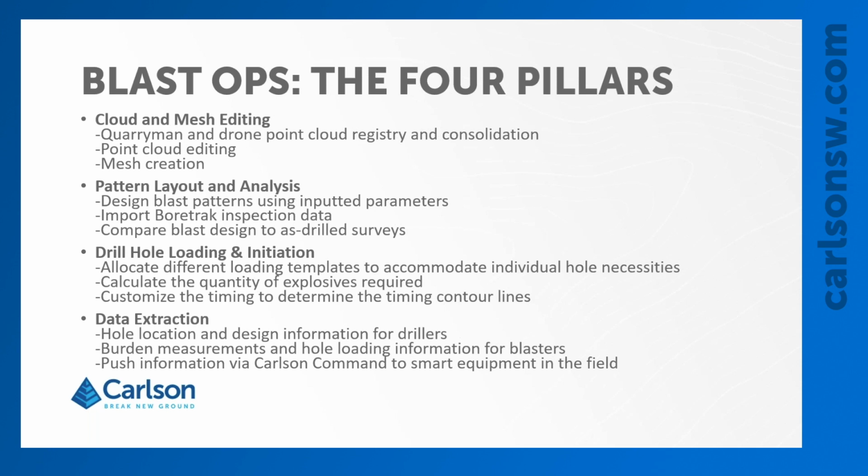Some of those things could be your pattern layout and analysis, your drill hole loading, initiation, creating your contour lines for the timing. And then with all of this, you have this ability to extract the data. You can send your hole locations out to GPS or to drills. You can send your burden measurements and hole loading information to the blasters. And you can push information via Carlson command to smart equipment. So you have this back and forth communication between the office and the field.